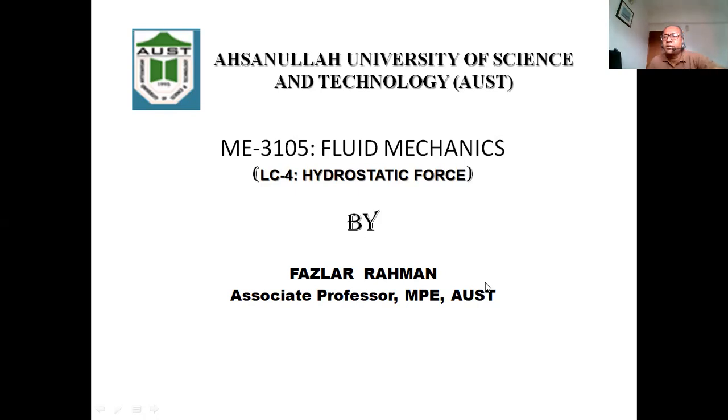a mechanical device. But we have a very good tool. Tool means an equation to measure the pressure at a certain depth of fluid. That pressure is P equal to H rho G, or we can say P equal to gamma H. This is a very good tool.